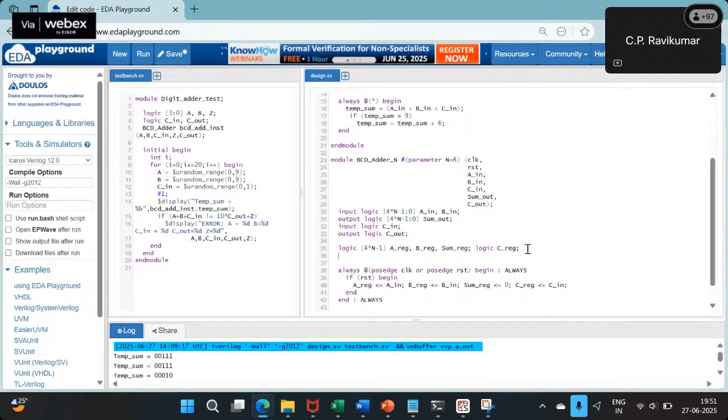So how big is that counter? It should be able to accommodate n. Three bit. So we need at least one extra, right? So 1 plus $clog2 of n, right? So if it is 8 bits, we'll have to check for 1000. So we may need one extra. Okay, count. And that count also has to be initialized to 0.